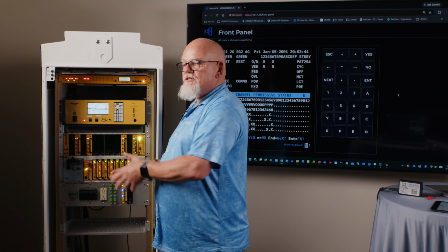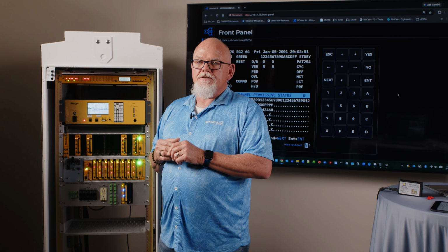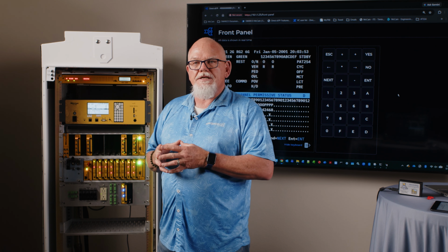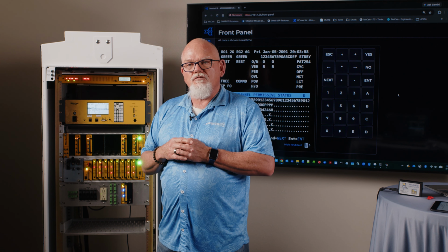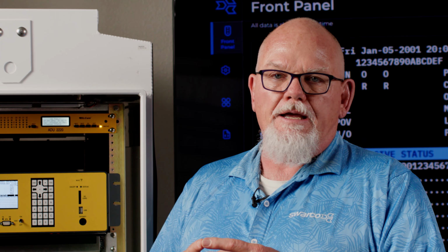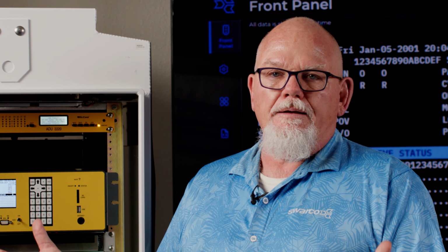It's a much more reliable cabinet because it's not prone to electrical variances and shocks and other types of things that would cause problems in a NEMA or a Caltrans cabinet. So again, much more robust. One of the things that the ATC cabinet is known for is its touch safe capabilities. Basically, a NEMA cabinet and a Caltrans cabinet has tons of exposure for AC, live 120 volt AC.